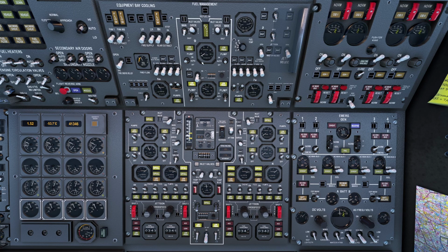I might have taken a bit too little because we have to empty tanks 5A and 7A, and as they are not correctly represented, they are gonna increase our trim to the front, so we have to trim more back. I still have fuel in number 10, which does not have that big an effect and is not as large. You see 3,600 kilograms, and I'm almost empty, but correctly at almost 59, so that was calculated correctly.